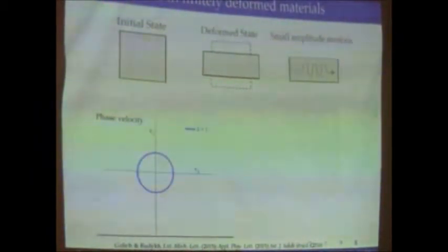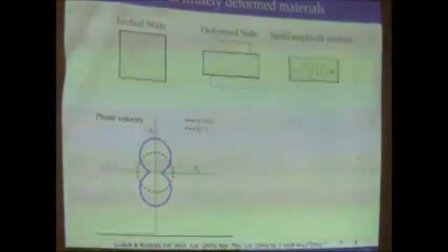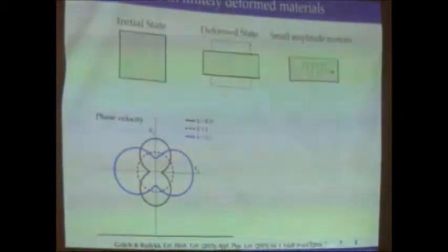I just would emphasize here how deformation affects the wave propagation, even in this homogeneous and very simple material. So here I plot the phase velocity as a function of the direction of propagation in the undeformed material. Once you apply deformations, different stretches, you can observe very different behavior. You can actually slow down or increase the speed of the elastic waves propagating in the material. Again, you can apply tension or compression, and that will change it.